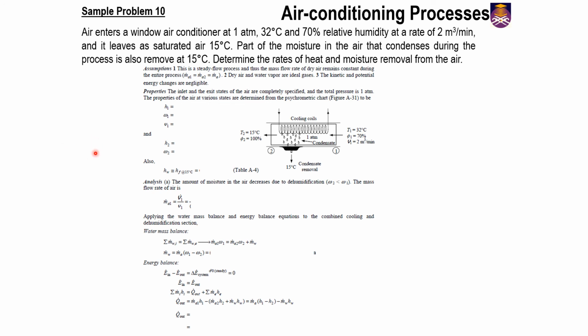All right. So you must also find your enthalpy. All right. So saturated liquid at 15 degrees C, right? Because this condenses at 15 degrees C. So you must find saturated liquid at 15 degrees C from Table A4.